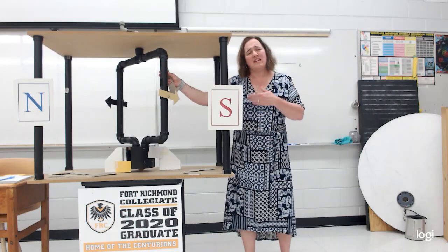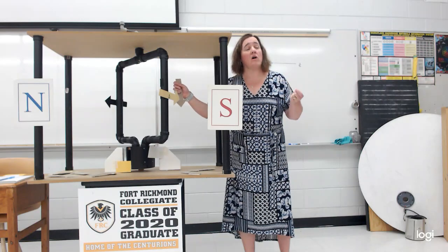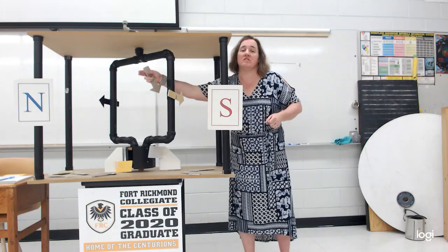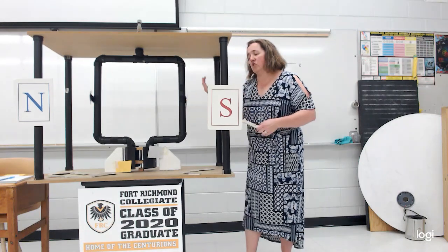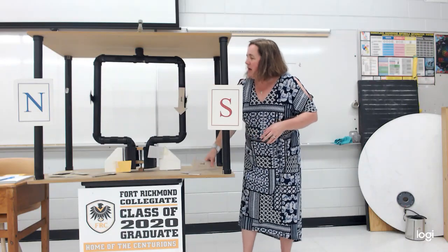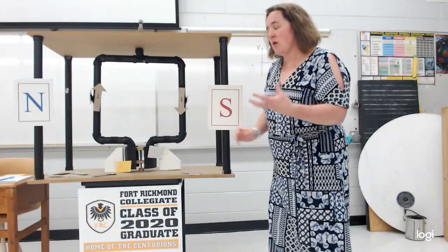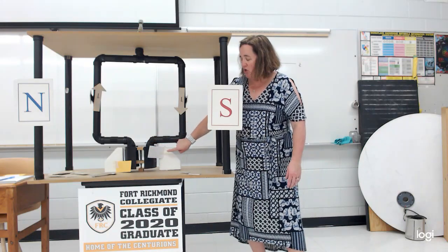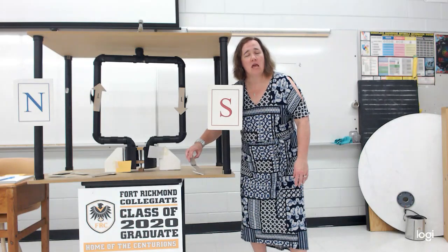So then I continue my rotation. Now you'll notice if I was at an angle, the sine of this angle would represent the quantity of the EMF, but to quickly explain things we're really only interested in the zero and the maximum value. So here I am again moving at 90 degrees. So velocity, magnetic field, palm facing down, we're getting current in here. And then over here, coming out of the page, magnetic field, current coming this way. Now let's trace it. It comes down, goes into the commutator, into the brush, and out through the external circuit. Notice the direction is exactly the same.